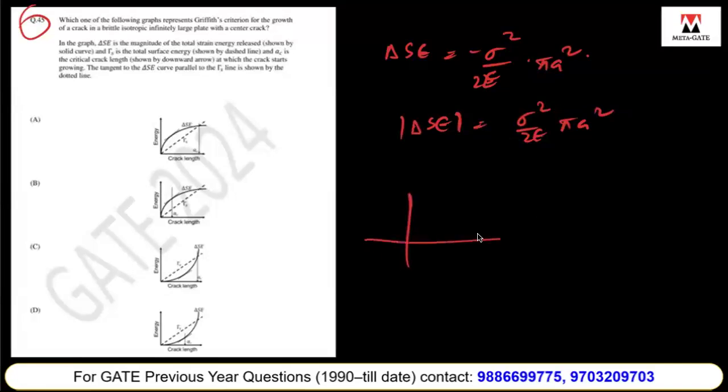So you know that delta SC will be upwards. Now, for the strain energy liberated by crack growth for forming a crack, the bonds must be broken, and the bond energy is in effect absorbed by the material. So the total surface energy is given by 2 gamma a, which is the energy associated with the crack length. These two factors, if you consider, tau s is a straight line. So this straight line will be like this.